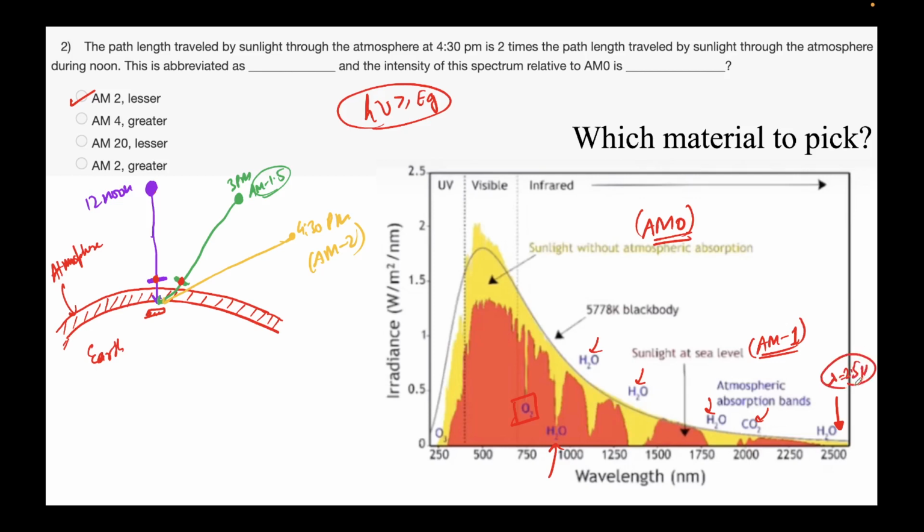If I put lambda equal to 2.5 micron, its band gap will correspond to this energy. If you recall the expression I talked about earlier, 1.2 divided by lambda in micrometers gives you Eg. So for 2.5 microns, Eg is, let's say, 0.5 eV.